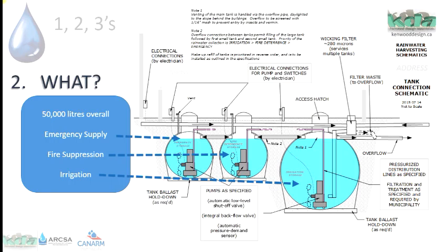This system is underground. The first tank on the left is for emergency storage if the power goes out, if the well goes down, if there's problems that they can't supply water to the house and the facilities, then they have this stored water there. The second one is fire deterrence. They're out in the rural area. They want to be able to control wildfire around their buildings with a specialized rainmaker type of thing, not an irrigation sprinkler, but a water wall type of sprinkler. So that's what that's there for, and that's for 60 minutes of pressurized spray.